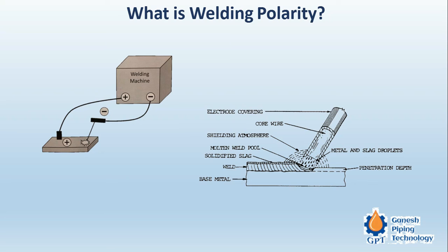Okay, so as soon as the arc is struck, the gouging effect will take place, and the electrode which is connected to the negative pole will start removing the weld. These electrodes basically are carbon electrodes, and they are used for the gouging process. So this is most common when we don't have the gas cutting facility.